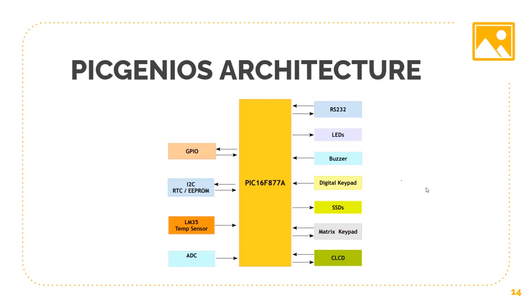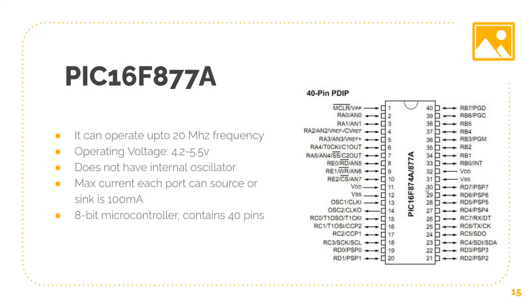It has a central microcontroller, a PIC16F877A, and there are a lot of other peripherals connected to it like LED, buzzer, SSD, CLCD, sensors, switches, and keypad, and a lot of these. For our project, we'll be making use of the buzzer, the keypad, CLCD, a few switches, a few interrupts, timers, and etc. If needed, we can even attach it with a motor or something else to simulate the washing machine.